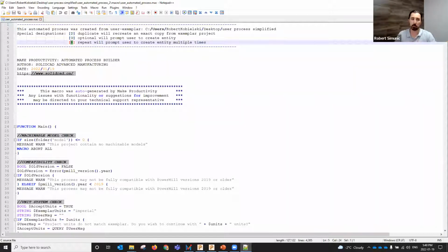So that's effectively dynamic. Whereas templates, typically speaking, when we save a template and the tool is saved in the template, that speed, feed, cutting parameters, they're kind of set in stone unless you revise the template, of course.